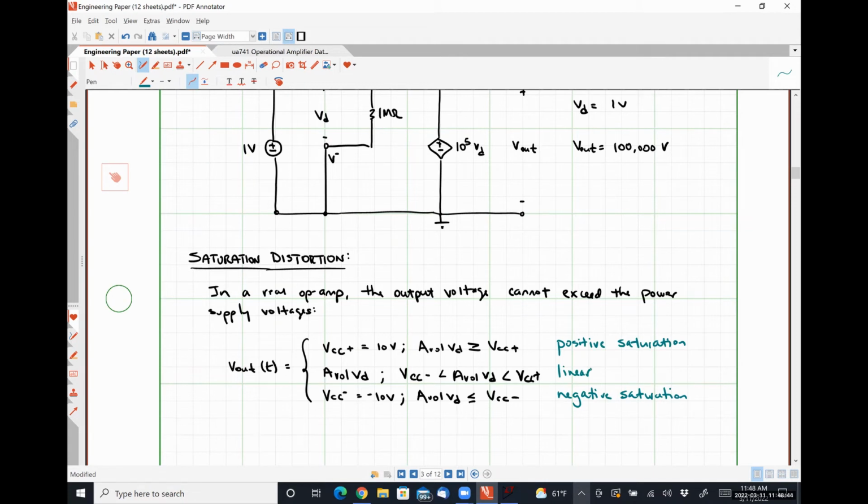So our model behaves exactly like it's supposed to under linear operation, and that should kind of make sense because our model is based on Thevenin's theorem, which says any linear two-terminal network can be replaced by a voltage source in series with a resistance, right? So our linear model is applicable when our device is behaving linearly, and it gets thrown away when our device isn't. Bradley.